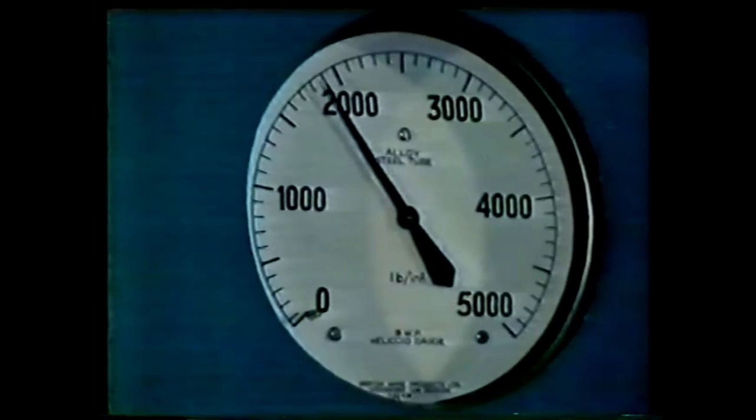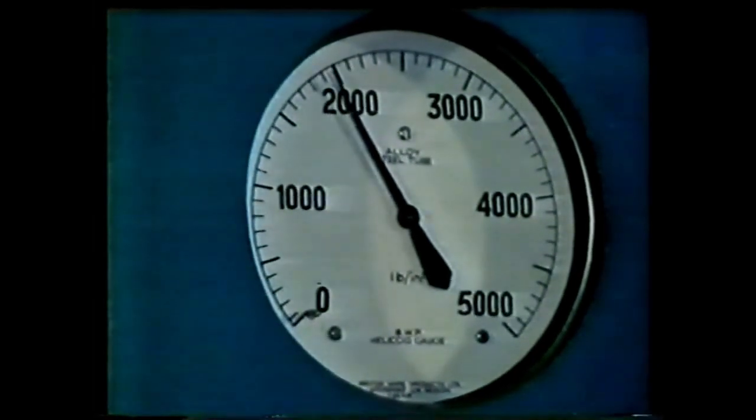The capsule is placed in the center of a high-pressure die in this hydraulic press. At the top and bottom are two horizontally opposed tungsten carbide anvils. At the back of this press, the heavy braided copper leads give some idea of the enormous currents which pass through the anvils to generate the necessary temperature. When the right pressure and temperature conditions are reached, the metal melts and acts as a solvent to recrystallize the graphite in the form of a diamond.